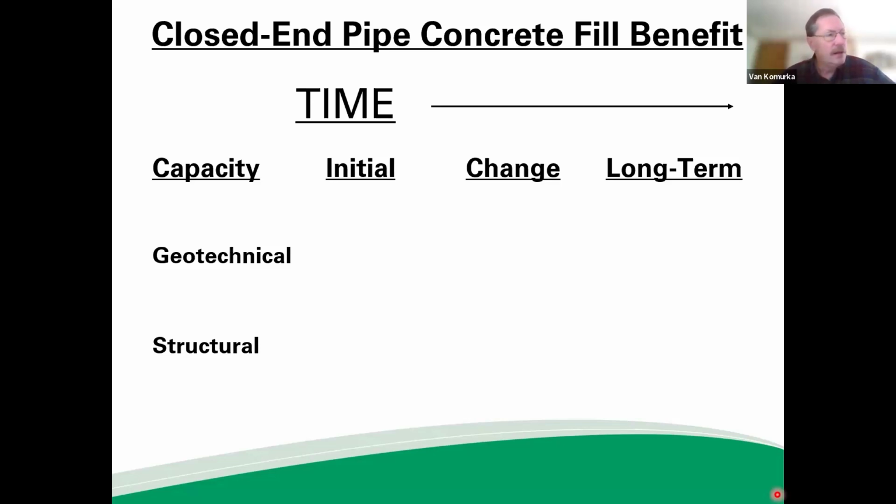This is a key point. Most of my practice has been done with closed-end pipe backfilled with concrete because they're the most matched up, if you will. They take the most advantage of setup. This is key. Concrete filled pipe piles are the only pile type that can have their structural capacity changed after driving.